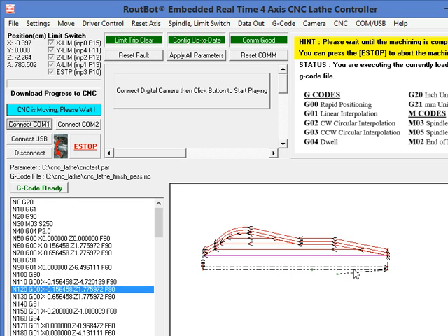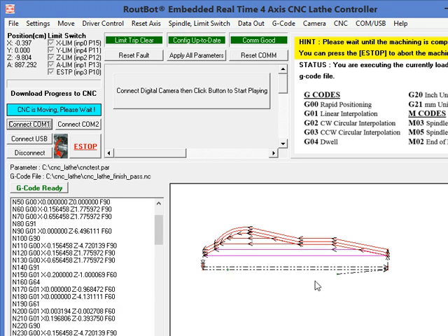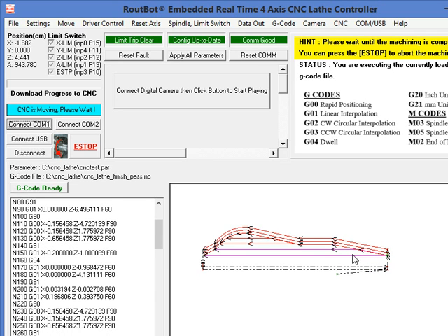As we can see, the roughing pass is always going into the material by the depth of cut roughing. In our case, the depth of cut roughing is 0.2 inch, so it will go into the material by 0.2 inch and then get out of the material following the profile, and always going back out by the 0.5 inch clearance to material that was specified in the wizard. So now it's ready for the 3rd pass.